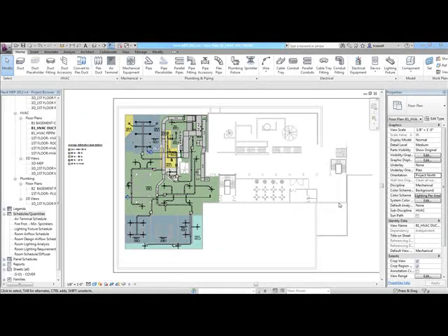I would like to start with talking about how Revit differs from CAD and other CAD applications. Revit is not vector driven. In other words, these are not lines, arcs, and circles that you're seeing on the screen at the moment. It's an object-based program. In other words, when I need duct, I'm going to create a physical object that Revit recognizes as duct. Also, Revit's database driven.